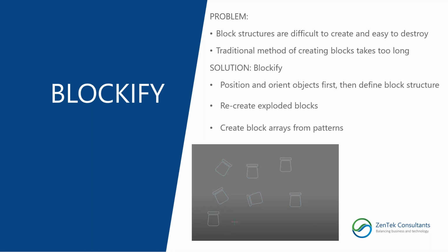Another use is to essentially undo the main issue with blocks, where someone goes in and explodes the blocks, and now you have to manually redraw and recreate them. Blockify does that all in one step. It recreates the blocks that got exploded, or it redefines them in the drawing structure.